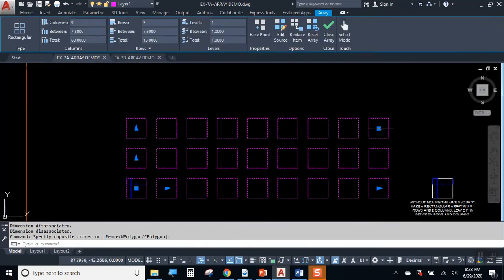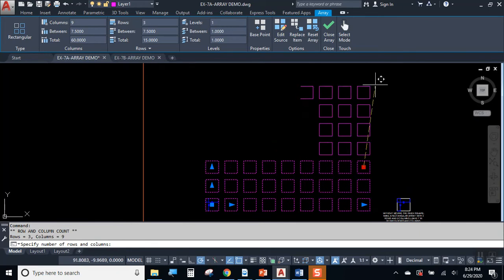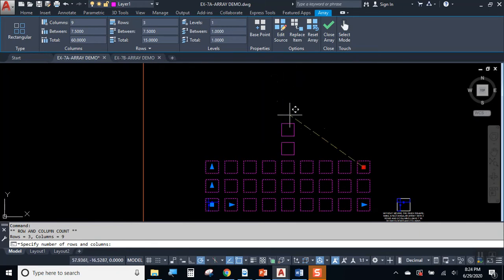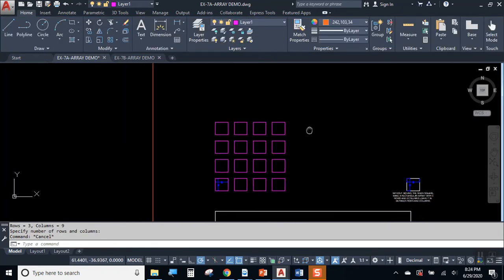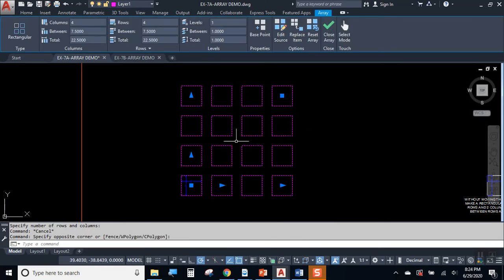And then clicking on the grip opposite the origin does rows and columns at the exact same time. Okay. Now what we've done is we've taken the original and copied it into a pattern that would be much easier than creating a pattern one copied instance at a time.